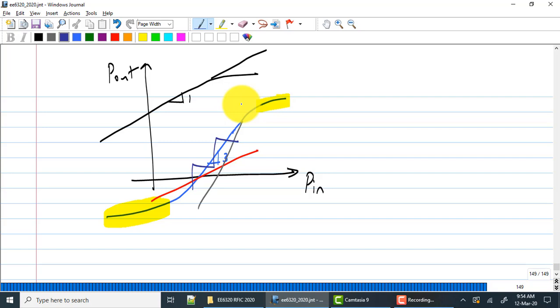How long does your IIP3 simulation take? 1 or 2 minutes? Maybe lesser, right? For your circuit, hopefully lesser. Then why only run for 2 points, right? Maybe every 5 dB, first do a coarse simulation from maybe minus 90 to 0 or minus 90 to minus 10, something like that. Run the sweep. Understand the curves. Then you can use a subset where it is linear.